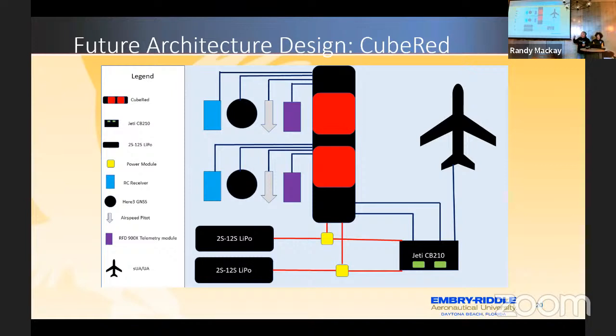So the idea would be things like a GPS is actually connected to CAN bus 1 and 3, and therefore it's available to both autopilots. In the QBread, we have 3 CAN buses to give us access to every single bit on there. We'll go into the architecture of this stuff in probably a few months once we get everything tested and proven. But we've basically got an architecture where the I/O structure is separated from the FMU in a way that either flight controller can get access to all of the I/O that's available.